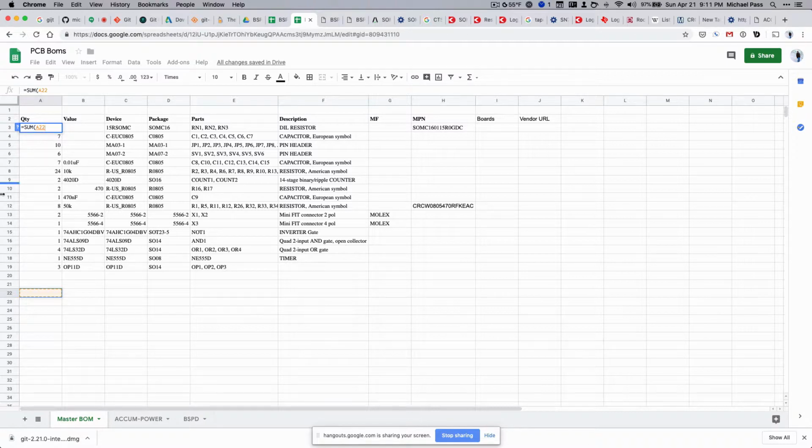It'll make the sheet a little bit sparser. The downside is that if you want to update the parts list for an individual one through EAGLE, or generate the BOM again, after it's already been compiled, we'll just have to manually update the sheet based on what the BOM is, and compare it manually, because it'll get too complex.